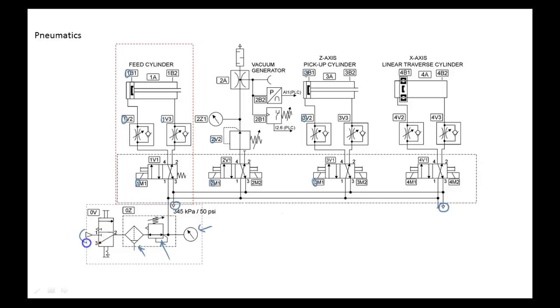And of course, this is the symbol for pressure. Notice these arrows are pointing in different directions. So this is our source. By the way, all these symbols would be basically the same for hydraulics, except they would be black, colored in. So if they're opened up like this, it means it's definitely pneumatic. If they're colored in, it means it's hydraulic.